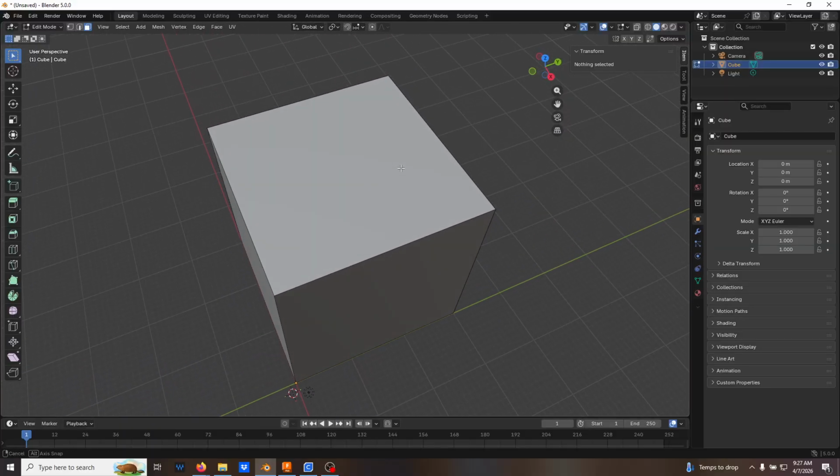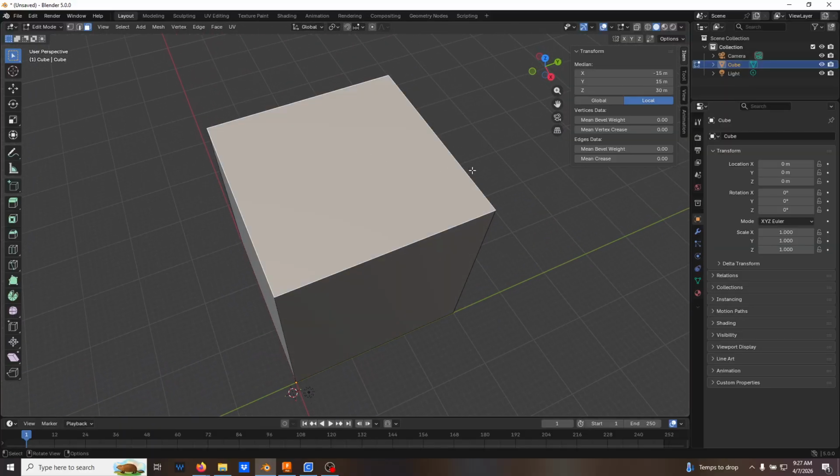And then what I'm going to do here is select this top face and use Control I for the inset tool. Oops, screwed that up. There we go. Select that face. I, not Control I, just I, excuse me. There we go for the inset tool. It'll only give me the thickness. I'll set the thickness to 10. There we go.